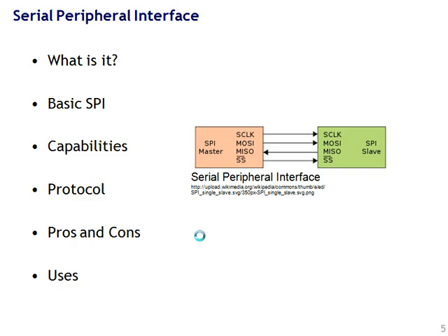But for very short range, you go at a very high speed. You have SCLK, that's the serial clock out. MOSI means master out, slave in. And here's master in, slave out. So they're paired. That's data. And then here's a selector, a slave select, or not slave select if you like.